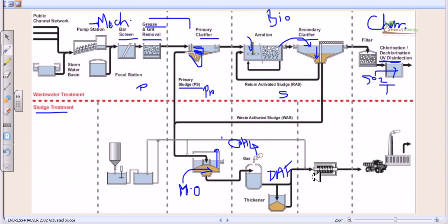So we dry them, we dewater them utilizing chambers, which are called centrifuges. And we know in scientific labs we have used centrifuges, and those are small micro centrifuges. But the centrifuges used in sludge dewatering are really huge, mega centrifuges. Now in this centrifuge the mechanism remains the same, so the water is placed at the top and the sludge is sedimented at the bottom. So it's a layer of sludge at the bottom. We just take out this sludge from this place, and the sludge becomes a solid cake-like structure.